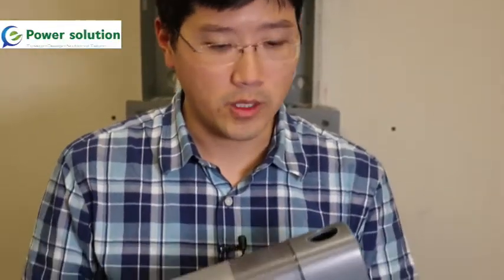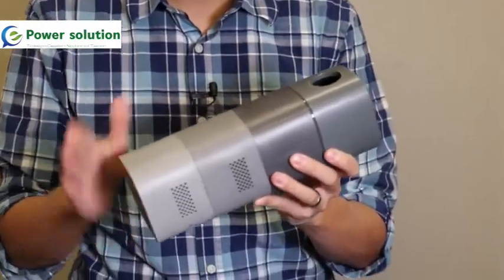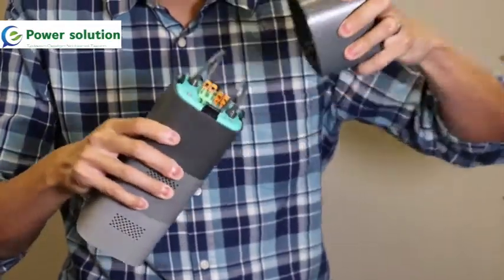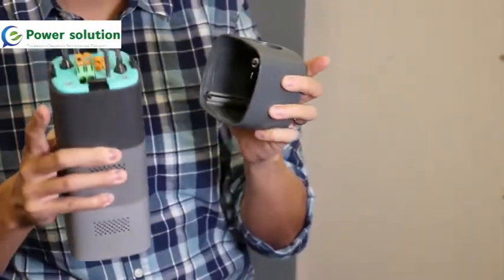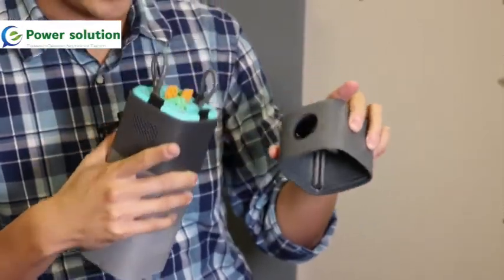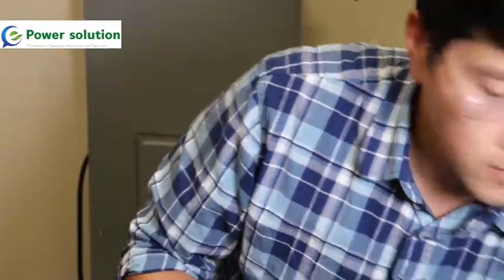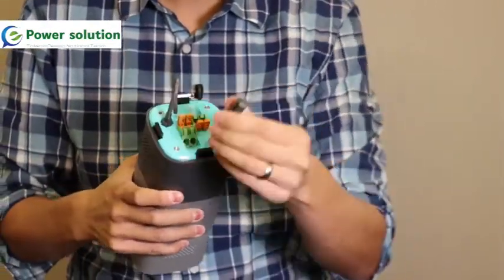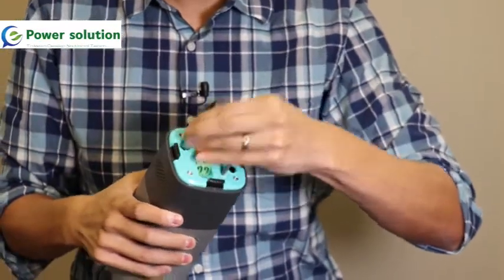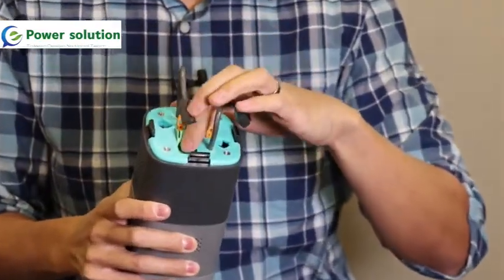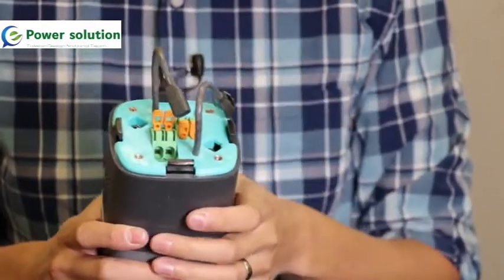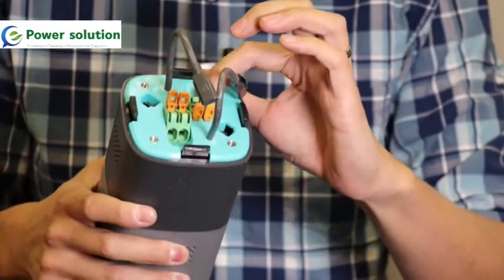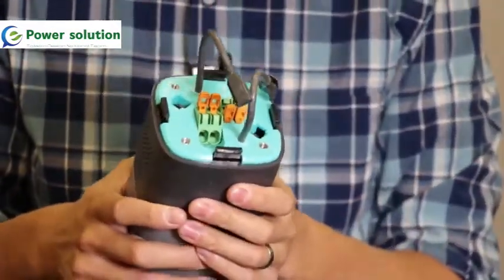This component of our system is our base transmitter. It's composed of 2 main sections, the main transmitter data collector and the field wiring compartment. The field wiring compartment is where we will route wires through into the panel through this conduit hole. The base transmitter consists of 2 data ports that connect to our sensors, as well as 4 voltage ports that will connect to the 3 phases of your power panel plus the neutral line. It will both sense voltage off these and power the system.